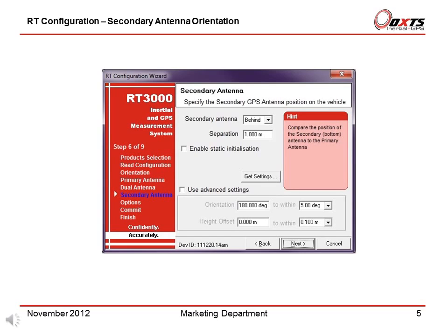Getting the angle wrong by more than 3 degrees can lead the RT to lock onto the wrong heading solution. The performance will degrade or be erratic if this happens. The RT does not estimate the distance between the two antennas. It is essential to get this right yourself, otherwise the system will not work correctly and the performance will be erratic.